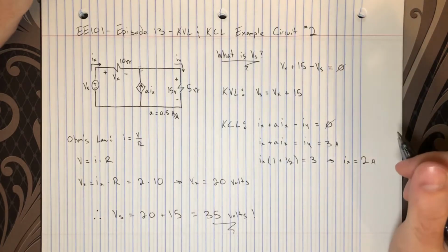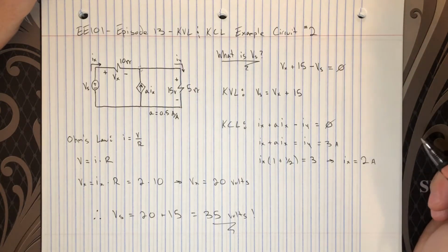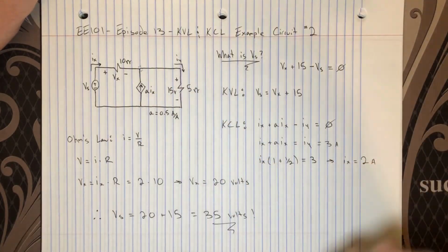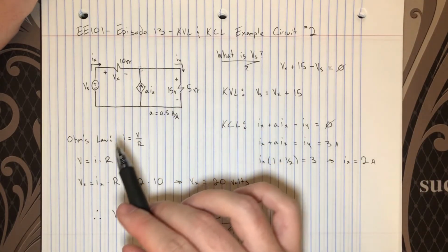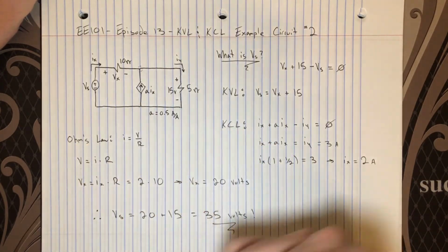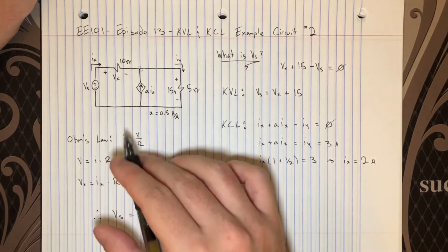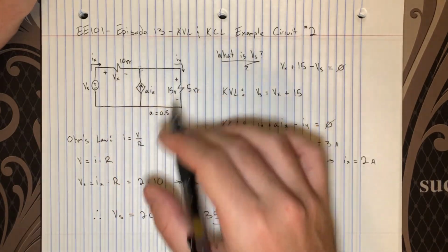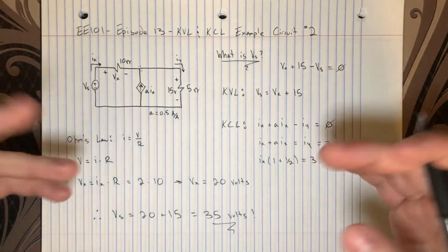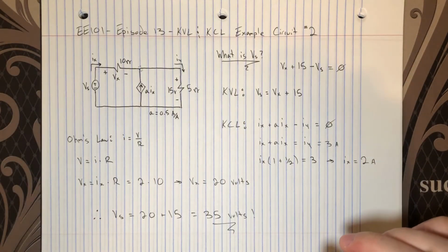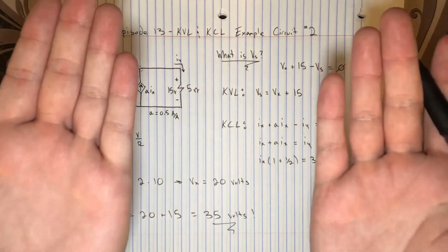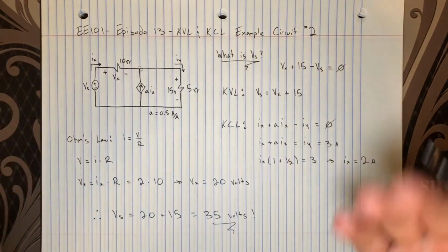Another thing you could do, like I discussed in the last video, is you could make sure that power is conserved. So you can think about how much power is sourced by all the sources combined, and how much power is consumed by all the passive elements combined, and then make sure that those two things are equal and opposite in magnitude, so that you have a total negative power that's sourced and a total positive power that's consumed, and if you summed them together it would be 0.